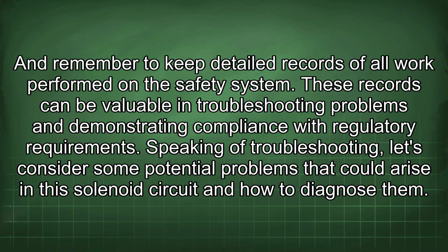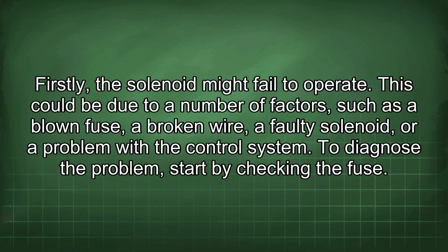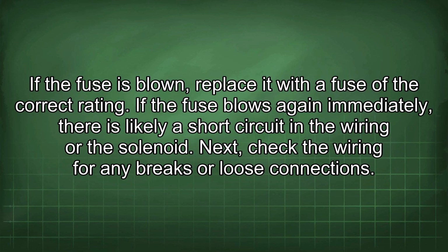Speaking of troubleshooting, let's consider some potential problems that could arise in this solenoid circuit and how to diagnose them. Firstly, the solenoid might fail to operate. This could be due to a number of factors, such as a blown fuse, a broken wire, a faulty solenoid, or a problem with the control system. To diagnose the problem, start by checking the fuse. If the fuse is blown, replace it with a fuse of the correct rating. If the fuse blows again immediately, there is likely a short circuit in the wiring or the solenoid.